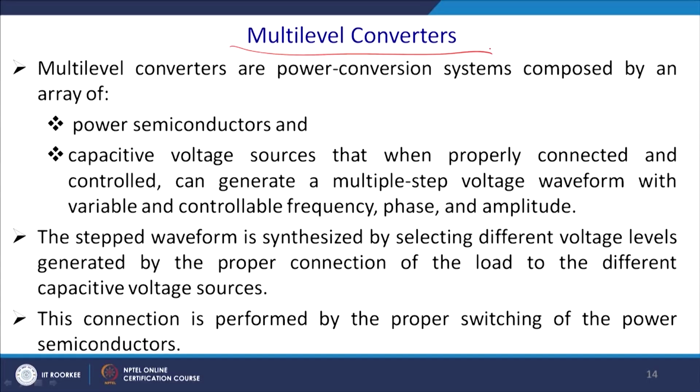Multi-level converters are power conversion systems composed of an array of power electronic semiconductors and capacitor voltage sources that, when properly connected and controlled, can generate a multiple step voltage waveform with variable and controllable frequency, phase and amplitude.